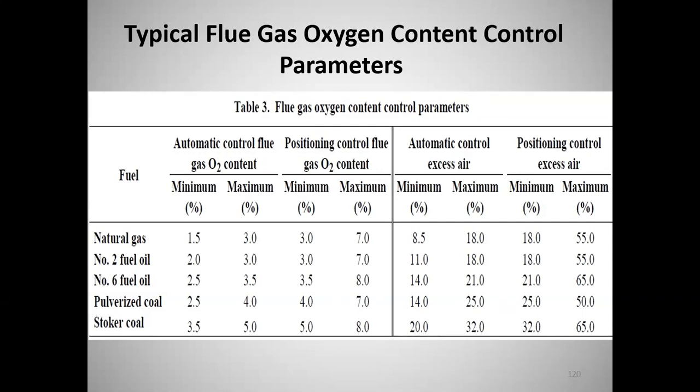So however much you need, if you need 10,000 CFM, you're providing over an extra 5,000 CFM that's just coming in. A little bit of that you need, but a lot of it's just coming in cold, going up hot, taking energy away from your boiler. So you can see.